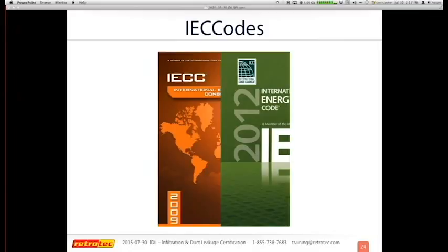That actually is one of our handouts, and Jay will post the links to send you directly to BPI, so you can download the field guide. I gave you some screenshots there, and that's exactly what you're being tested on. And ironically, the last line tells you the math. It tells you how big of a house you have to do your calculations for, so there are no surprises when you're taking this exam. So I know that my area for my duct tester is 1100, and my envelope is 14,300 cubic feet. Hopefully that helped.